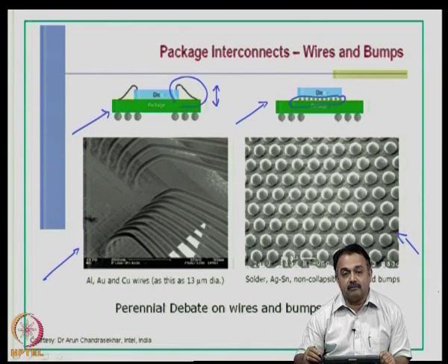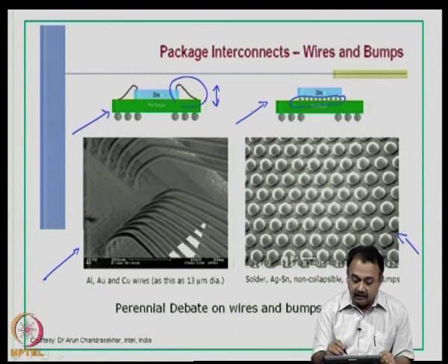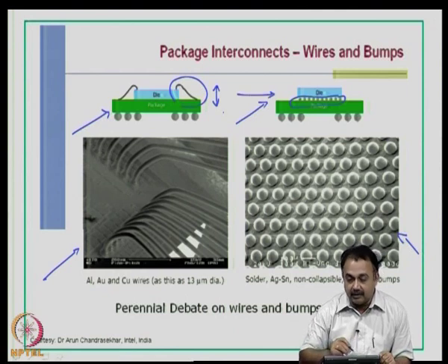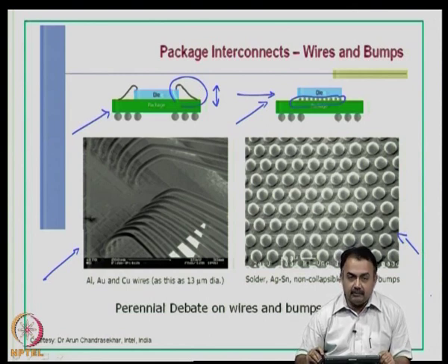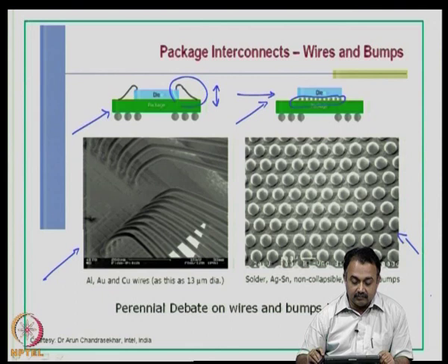If it is going to be small, then you can look at utilizing solder bump technologies, which are much suited for low profile packages, small outline packages and CSPs. There are many other issues also in terms of electrical characteristics and thermal issues.